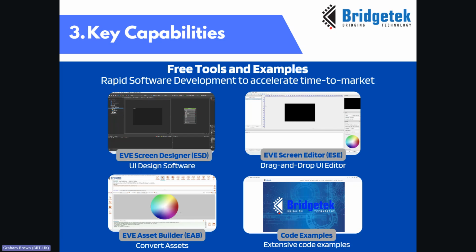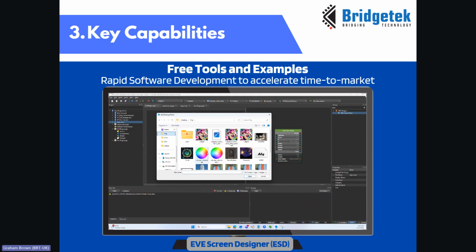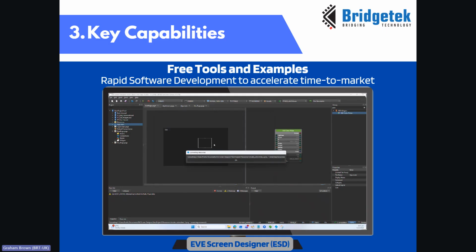Thank you, Graham. So yes, to aid in software development and application development, we have a suite of free software tools and examples that are available for use. The first of which is our Eve Screen Designer toolchain. Now, this is a full what you see is what you get editor, which will allow you to generate a full project application, including multiple pages and the logic between these pages. This can output full application code, which can be ported to your MCU of choice.